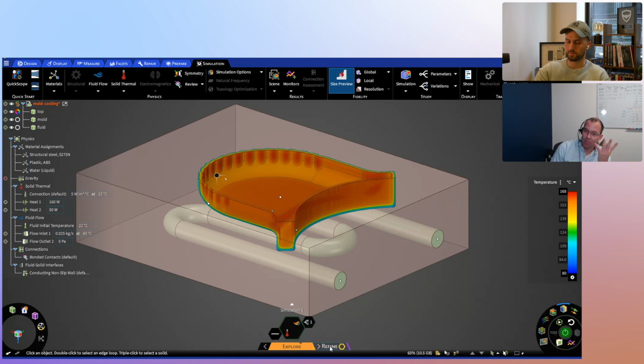And then level 4, because there's always another level, Jousef, of course, is up here in the upper right-hand corner. If my comfort zone is Fluent, like mine is, if I know the tools in Fluent and want to add in things like phase change, multi-phase, all that stuff, I literally can transfer this straight into Fluent. I've got all my materials, all my boundary conditions, all my cell zones, and from there I can start to add in more and more detail.